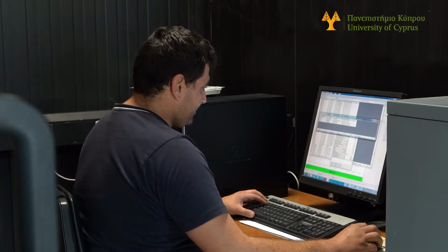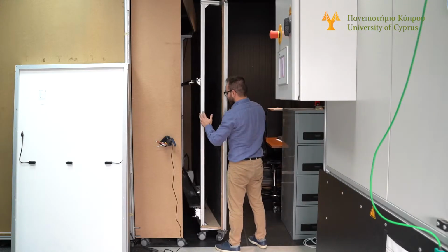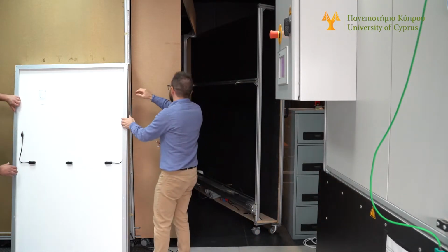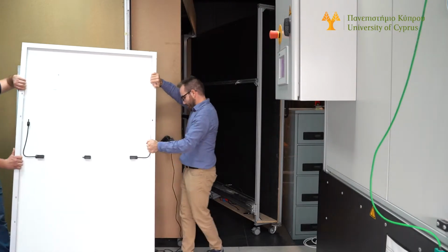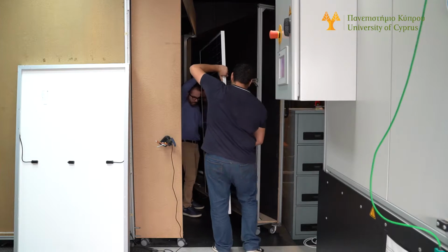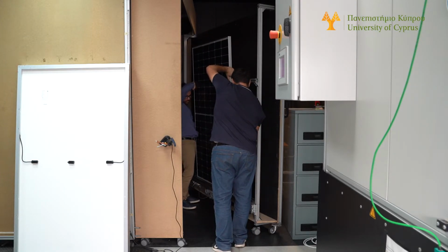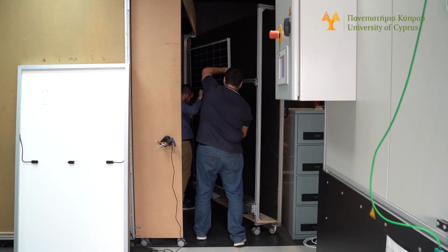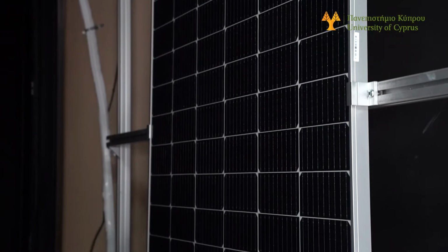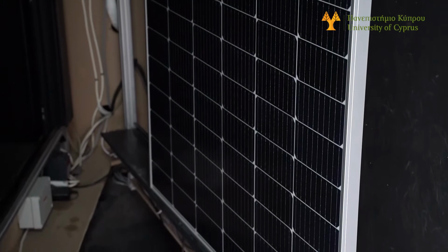This apparatus is a sun simulator that can test the photovoltaic module under standard test conditions according to standard IEC 61215. It's one of the most important devices of our indoor facility because using it we can get the IV curve of the photovoltaic panels at STC and verify their performance and degradation either before or after any test or the outdoor installation.